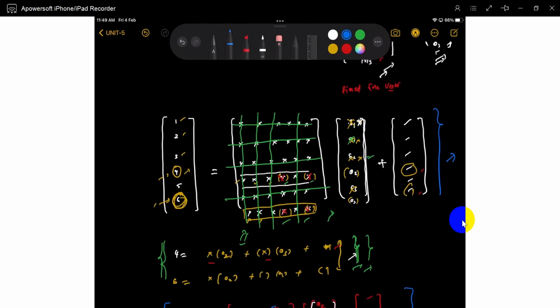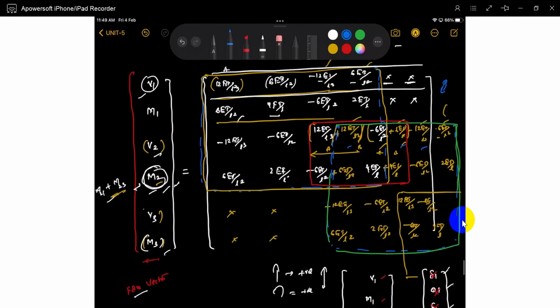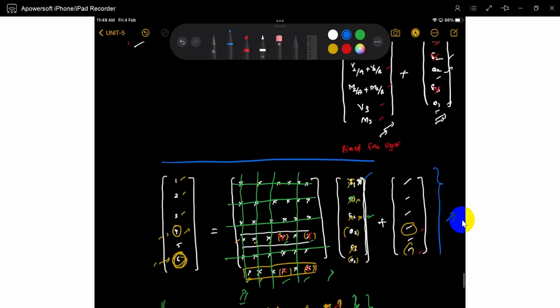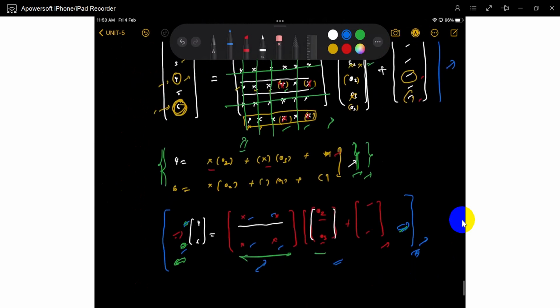So if you know this matrix, the first matrix, first element, second element, how they join and how they assemble those matrices. Later, if you apply the boundary conditions, these are the boundary conditions. If you apply the boundary conditions, you eliminate those rows and columns. What is remaining? You can solve those two. These are the known values. Only 2 unknown values. You can solve it directly.